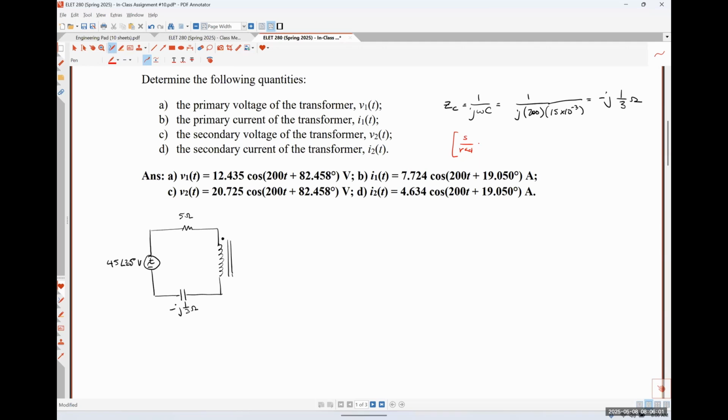Well, capacitance is measured in farads, where a farad is an amp second per volt. Since I have the reciprocal of farads, I'm going to have amp seconds in the denominator, and volts up here in the numerator. So we should be able to see that the seconds cancel seconds. Radians are a dimensionless quantity, so they don't really do anything at all. And what we're left with is a volt per amp, which is the same thing as an ohm, okay?